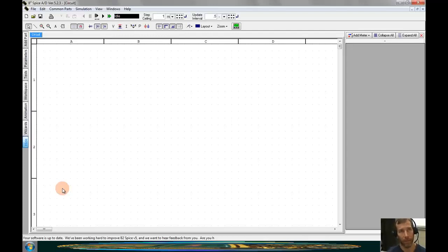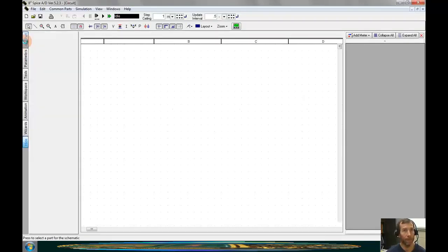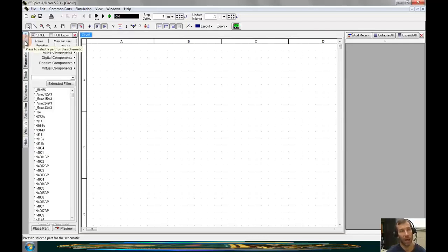This is the schematic background. The schematic that we're going to construct consists of a DC voltage supply, 2 resistors, and a current source. The schematic is on the second page of the SPICE handout. To add parts to the schematic, we have several options. On the left-hand side of the screen, we have an Add Parts tab. This will allow us to see all the parts that are in this program's library.